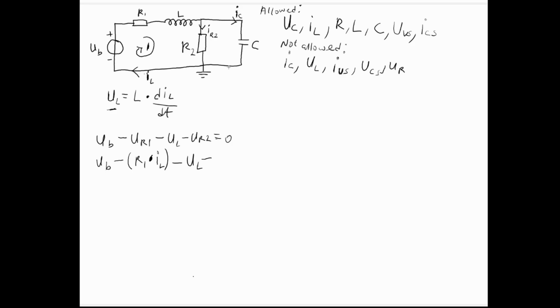Now, another very important tip I want to give here is this. Whenever you see a resistor in parallel with a capacitor, it really makes your life very easy, because the voltage across a capacitor will be equal to the voltage across the resistor. And the capacitor has to be on its own, with no resistor in series with it, just a resistor in parallel with it. It's a beautiful thing.